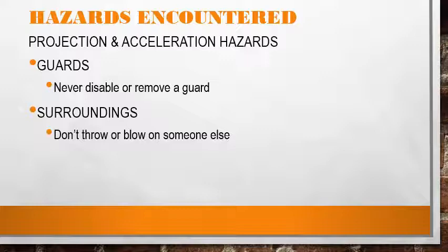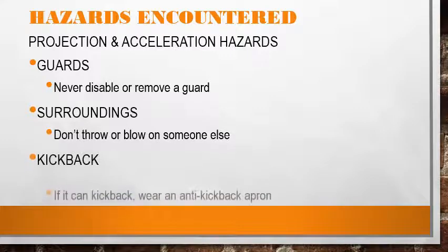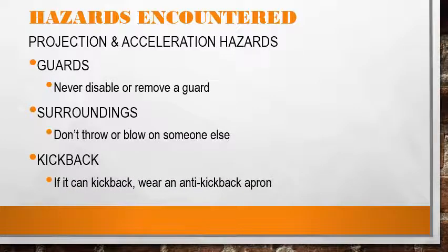If you don't like the grinder guard getting in your way while you're working, you can reposition the guard, but you cannot remove it. Always check your surroundings. Don't throw or blow projectiles onto someone else. Be careful about kickback. If a tool can kick back, make sure you're wearing kickback protection.